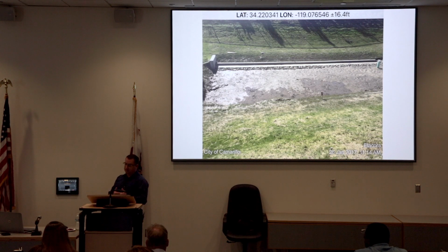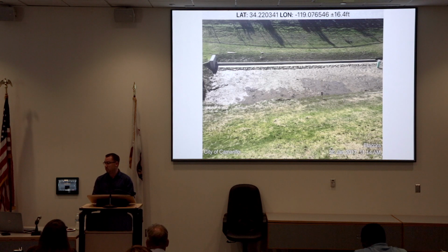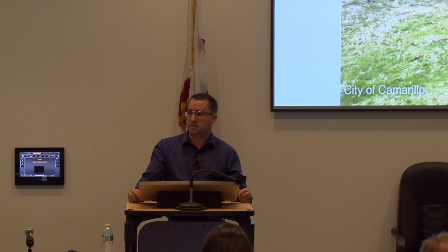I believe it calls out the same 50 feet away from service stations or any of those areas that would be high pollutant concerns. So if their site is sufficiently large where they can infiltrate in a different area, but they're not taking the drainage from that high contaminant area over to there, then it might work. But otherwise, they're going to probably have to use a proprietary device and treat 150%.